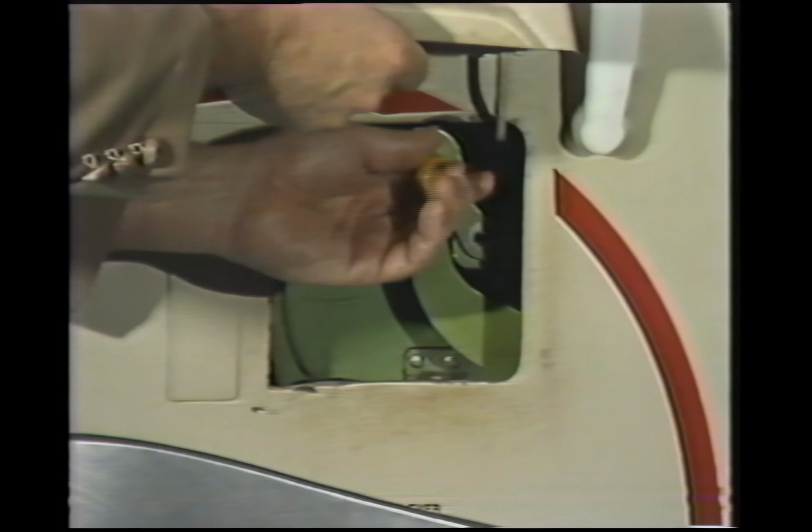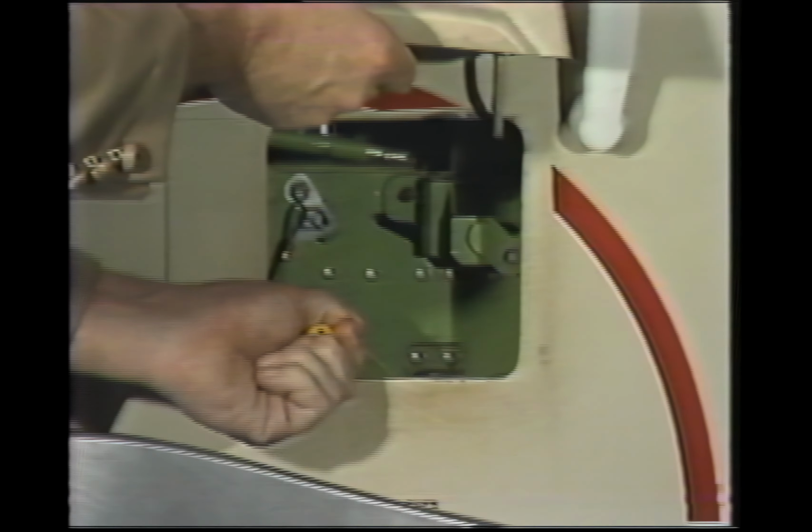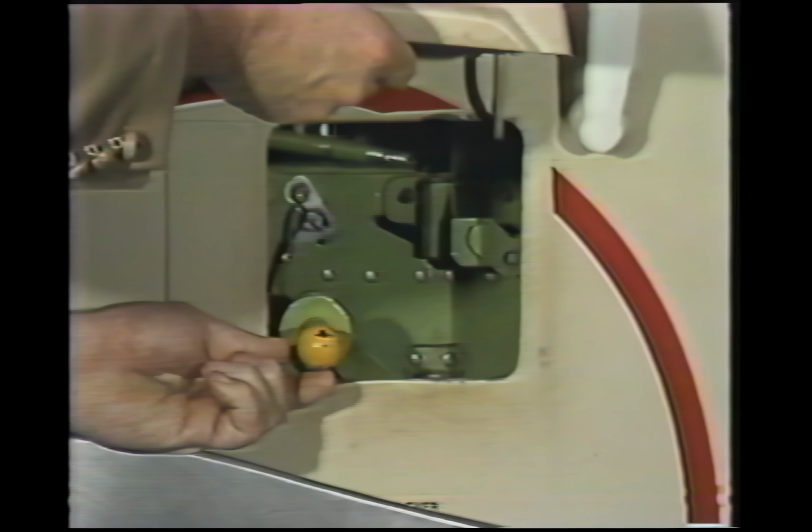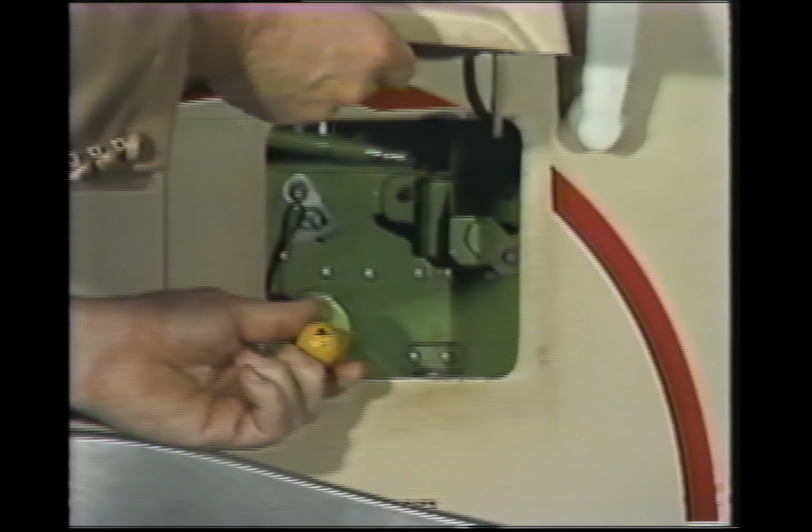To select the mode, raise this cover and move the mode selector handle either down to automatic or up to manual. This device with the green ribbon attached is the door safety pin. Each time the doors are placed in the manual mode, insert the pin. This will prevent accidental slide raft deployment.